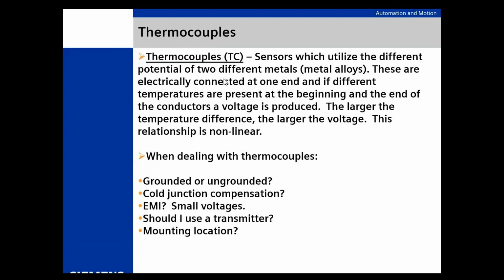I'll make a statement here that may get me beat up, but I'm going to make it anyway. Everybody's controller works. Everybody's. They work fine. It's the loop itself. It's the instruments. It's the things going on out there that affect it that make it not work. Everybody's controller will work in its envelope, but you put a bad thermocouple in the wrong place, and I'm getting a noisy signal, you're not doing me or you any favors. Pay attention. This is where paying attention to all this stuff will make your control life so much easier.